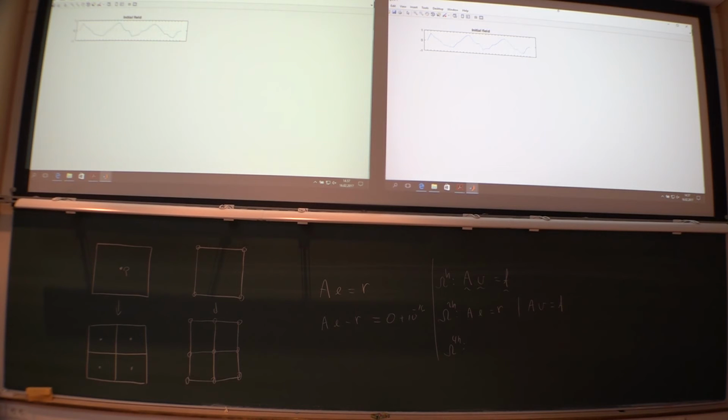So then some iterations on the fine level. Remember, it has to be smooth before you are capable of transporting that one to a coarser mesh system. So to the right, I now have the residual on the fine mesh. Now push that one down to a coarser mesh. That's a decent representation of the signal, isn't it? Not that bad, at least. Then we do a couple of iterations on this level.